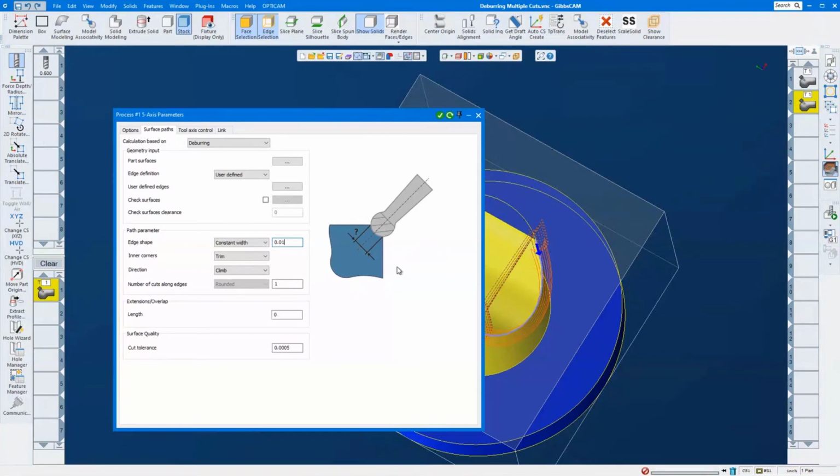So again, if you're locked in a 3-axis toolpath, then there's only one spot on that tool that it will be able to do that. But yeah, if you could make it so you don't worry about how much you remove from one face versus another, and you just want to break the edge no matter what, then you could define a point on the ball to do that. I'll send that in as a request.